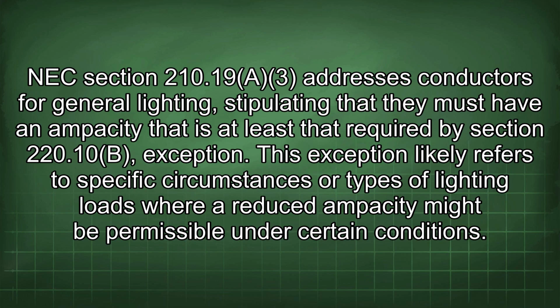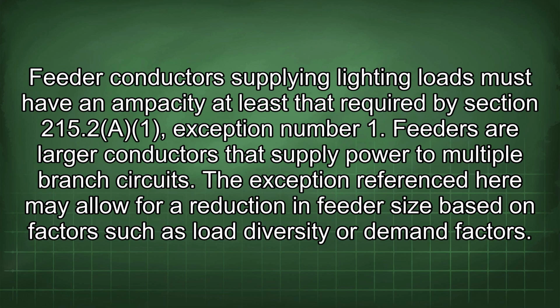certain conditions. Feeder conductors supplying lighting loads must have an ampacity at least that required by Section 215.2(A) exception number 1. Feeders are larger conductors that supply power to multiple branch circuits. The exception referenced here may allow for a reduction in feeder size based on factors such as load diversity or